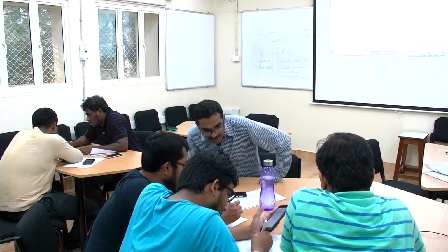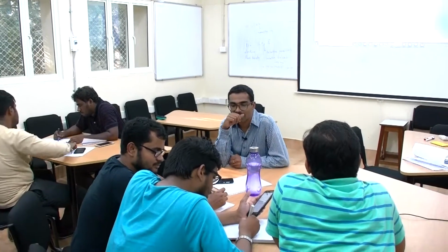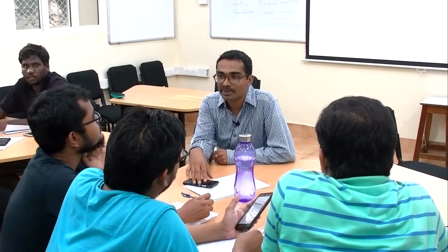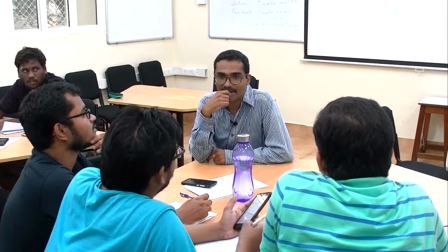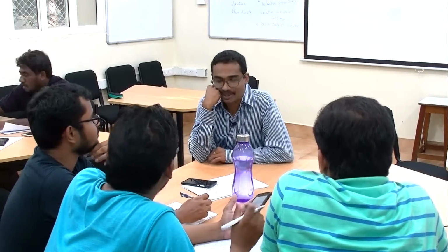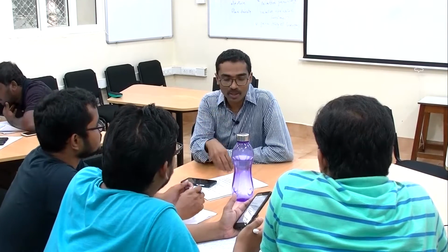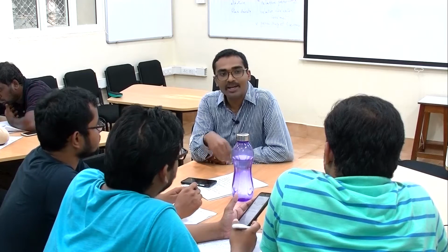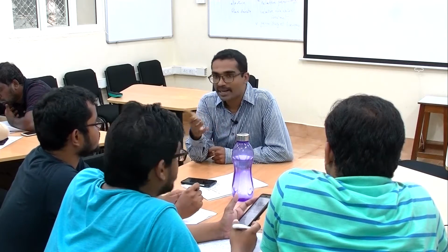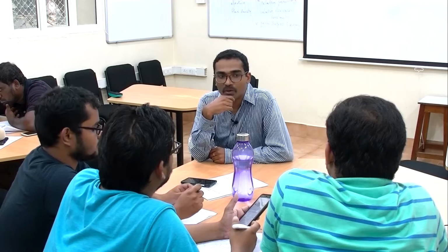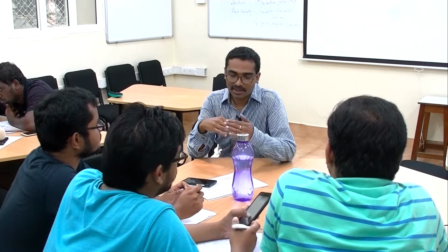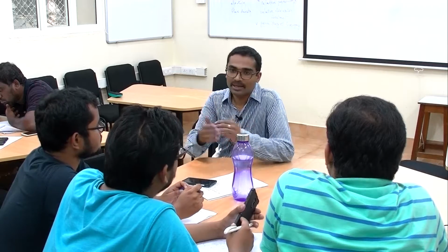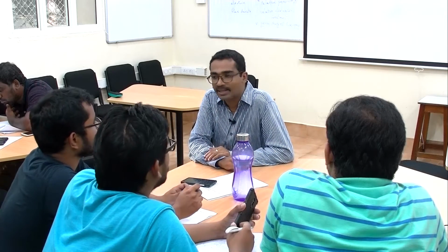So what are your observations? What trends are you noticing about relative permittivity? What kind of chemistries give rise to high relative permittivity? This is low frequency dielectric constant. Correct. So if you have atomic composition such that there is higher dipole moment possible in the material, it results in higher dielectric constant. And of course, if the atomic arrangement is such that there is dipole moment possible because of just atomic arrangement, then that would also increase the static dielectric constant.